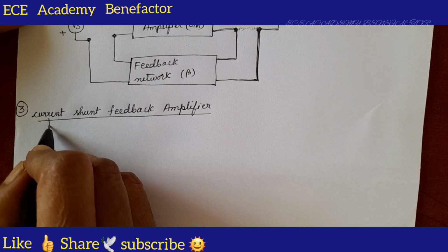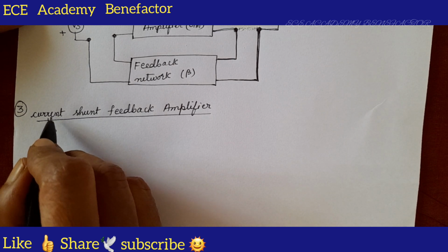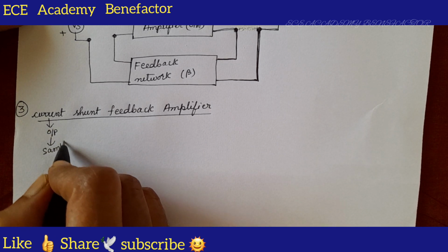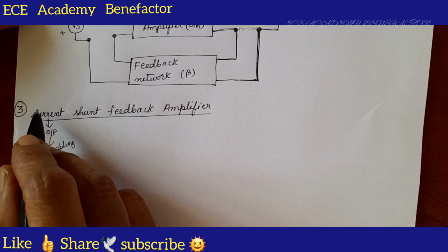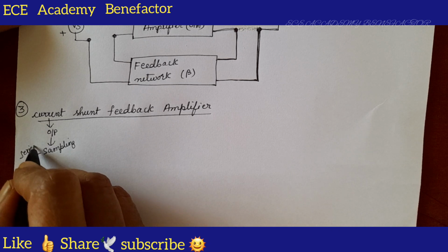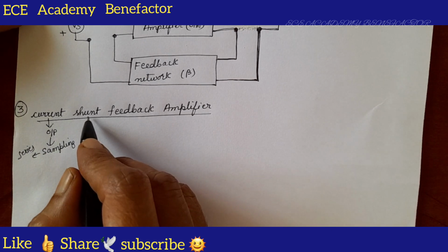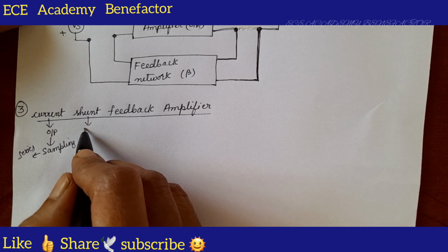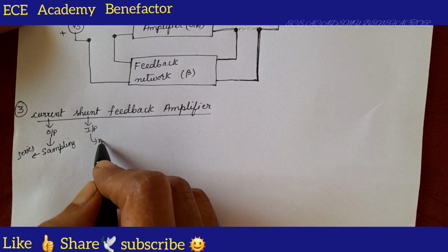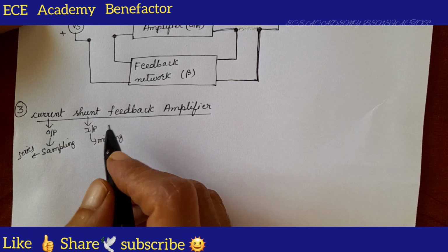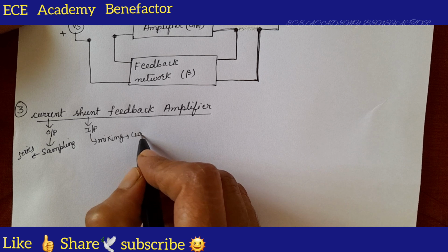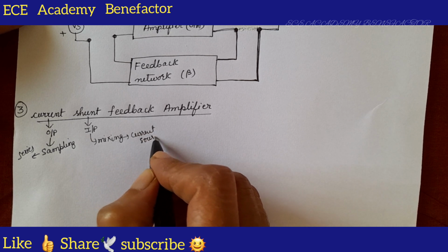The first word, current, indicates the output. What is done at the output of the amplifier? Sampling is done. What type of sampling is done? Current sampling. If it is current sampling, what connections are to be done at the output side? Series connection. Next word is shunt. This tells about the input side. Input shunt mixing is done. If shunt mixing is done, what source do we need to place? A current source. Current source is to be placed.